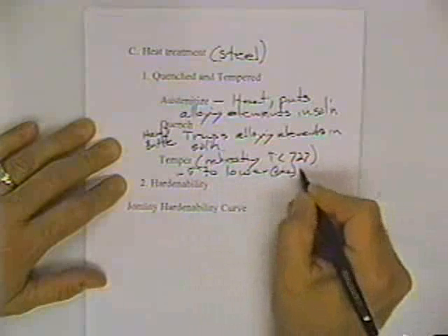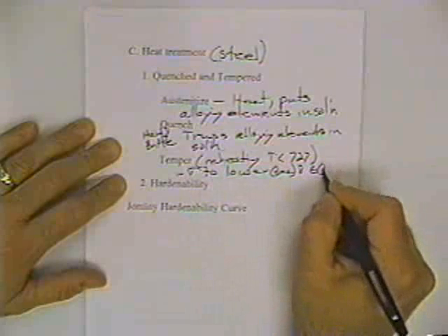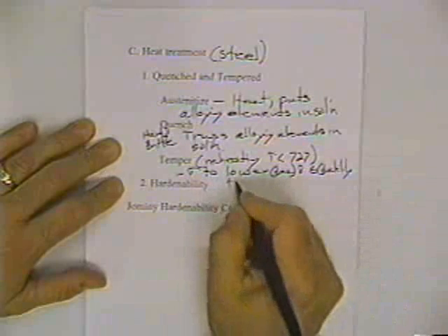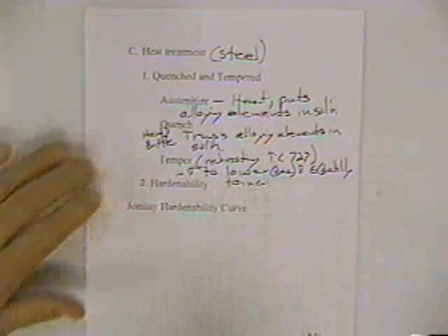lower or decrease and ductility to increase. So it's possible by a heat treatment to make materials change the microstructure so you can strengthen it by a heat treatment operation. And these strengthening mechanisms are interesting. We can add alloying elements, we can cold work, and we can heat treat. And many of these are additive so that you can combine their effect.